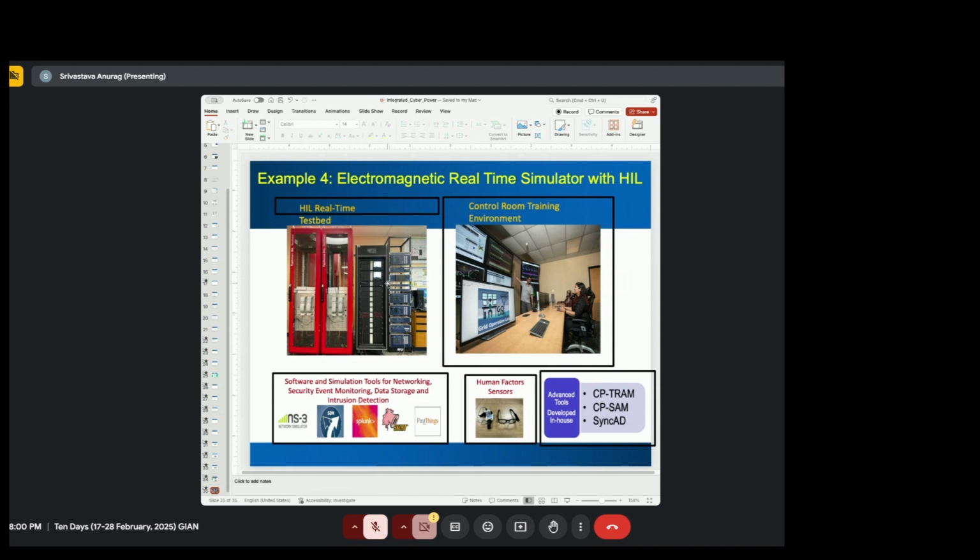Again, this one has very specific requirements of this test bed, where the transmission system needs to be modeled with detail of DERs, because that's where the attack can originate, with the generator, which the attack can generate, with the tie relays and PMUs, but it also has a limitation. We cannot model a big system here, right? We were at less than a 100-bus system. We cannot model all the DERs in detail because Typhoon can only represent certain batteries and certain distributed generators like solar.